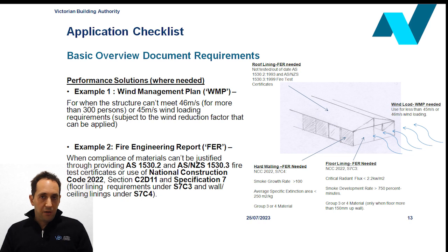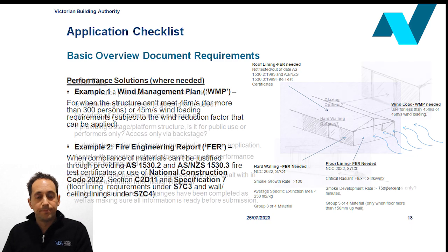But if it's to be, as you can see in the diagram, a Group 3 material, or simply you can't make the material comply, then you might have to look at getting a fire engineering report, or additionally you might have to think about choosing a different material.